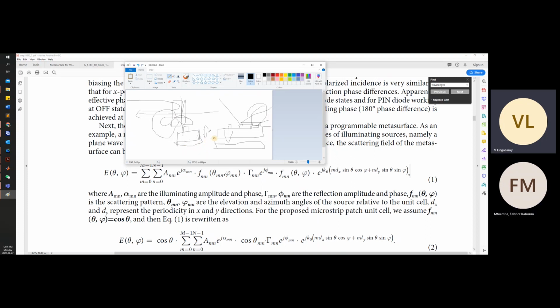So in order to get the in-phase component, we use a substrate of only 0.8 mm or 0.5 mm, right? If you are using an artificial magnetic conductor here, whatever gets reflected is reflected with zero phase. Therefore, it constructively enhances the gain of the antenna, basically. So in general they use it for that, and for some other purposes, they use it to suppress something. So many applications are there.